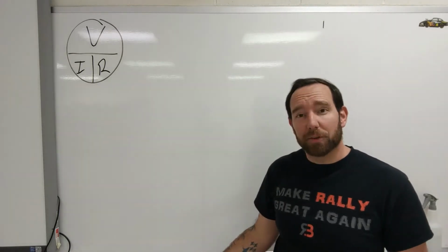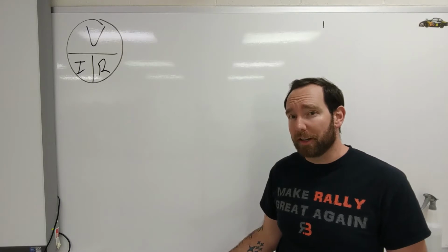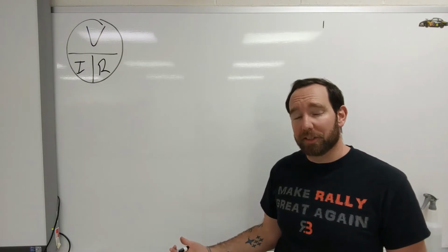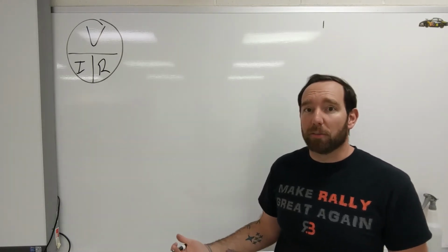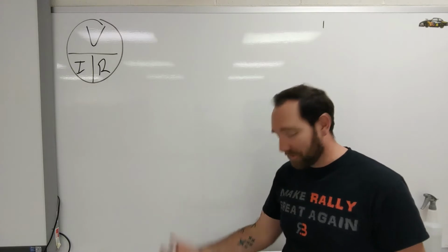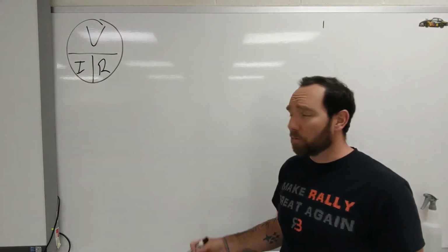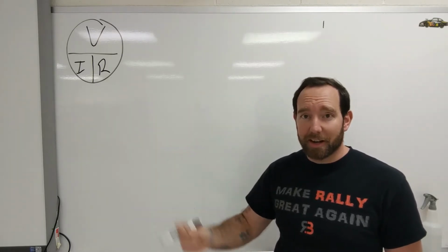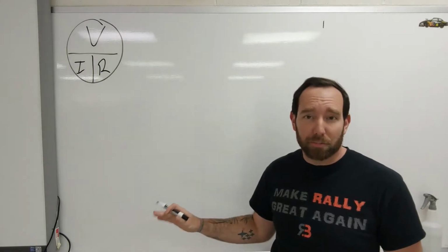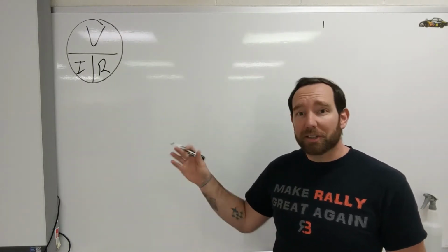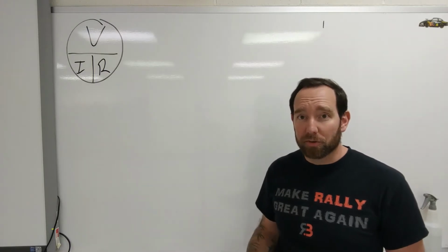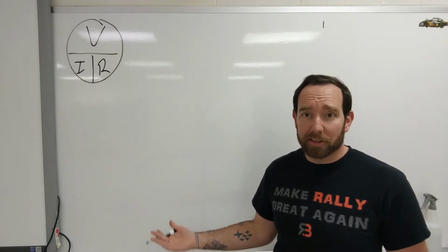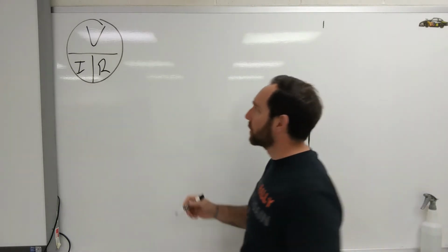The other equation that we need was given to you in the question, which is just calculating total resistance. And actually, if you guys remember back to basic series circuits and calculating resistance values, that's also something that you probably already knew. Maybe didn't realize it because of what you were looking at. And remember, in a series circuit, which basically has a start line and a finish line, we aren't dealing with any extra branches in this circuit. We just add up the resistances, and that gives us total. So if we have 2 ohms on one thing, 2 ohms on another, 4 ohms of total circuit resistance. Not too bad. Let's go ahead and draw this circuit on the board.